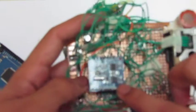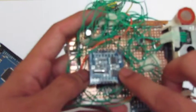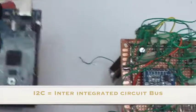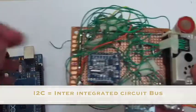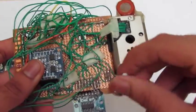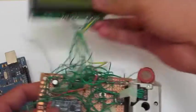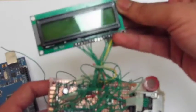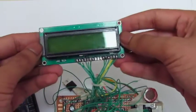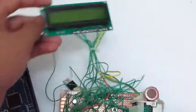We have a real-time clock, this is known as the tiny RTC, and it communicates with the Arduino using the I2C bus, and I've mentioned details about I2C in my criterion B. We have a potentiometer, that is a variable resistor, in order to control the brightness of the 16 by 2 character LCD. That is, it can display 32 characters in total, 16 per row.